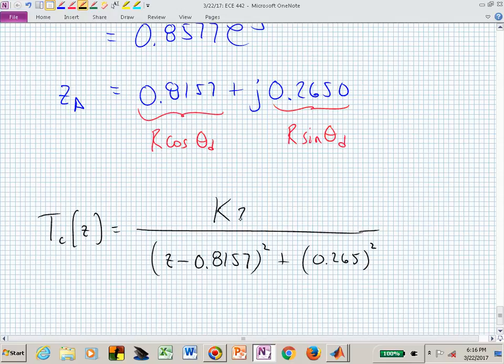Let's go ahead and just put a z there, and a z there will give me a 0 at the origin. I have a z over a z squared, which gives me just a 1 sample period delay between my input and the output, instead of a 2 sample period delay.